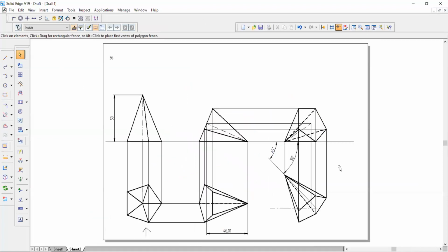Okay. So that is how you're going to do problems based on slant edges. Any problem if he is giving a slant edge or slant triangular face, whether it is direct or even if it is given as a beta angle problem, you must be able to do this. So this will complete your basic prisms and pyramids. Other special cases are there, that is cube, problems on cone, problems on tetrahedron. Those particular things will be very, very useful. So those things you must go through.